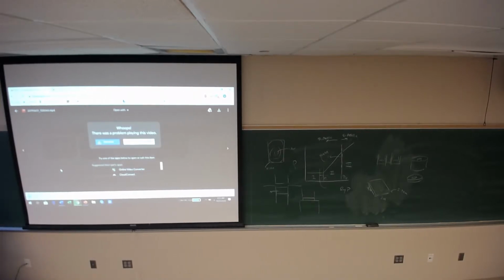Why do we prefer porcelain as a flooring material? Number of reasons, right? One, less expensive than natural stone. Two, it's impervious, so you don't have a problem of discoloration or absorption of things that are spilled on the floor. And three, it has superior wear resistance.